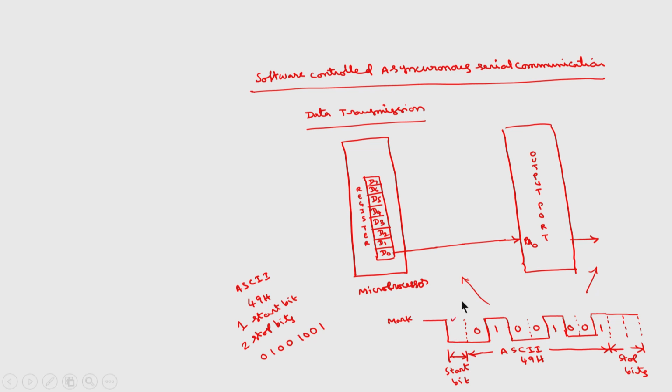First I will send the start bit; I can write the program later. Then this bit 0 I have to transmit: take this data into some register and transmit the LSB position onto port A, PA0, then shift the data towards the right and transmit again onto PA0, and set a counter for the number of bits to be transmitted. After this count is over, we stop. This is the counting operation.